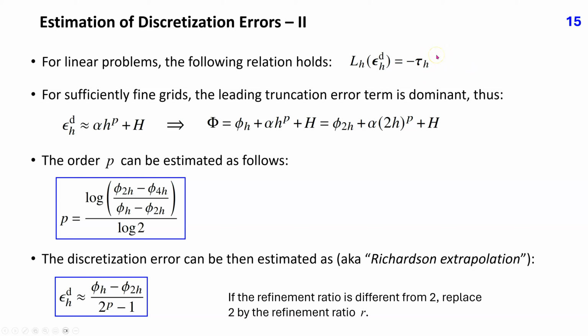Because the conservation equations are in general non-linear and the truncation error is never known, this equation is not of a great value. However, we shall see in the next lecture series how it can be used to estimate discretization errors and thus guide local error-guided grid refinement.